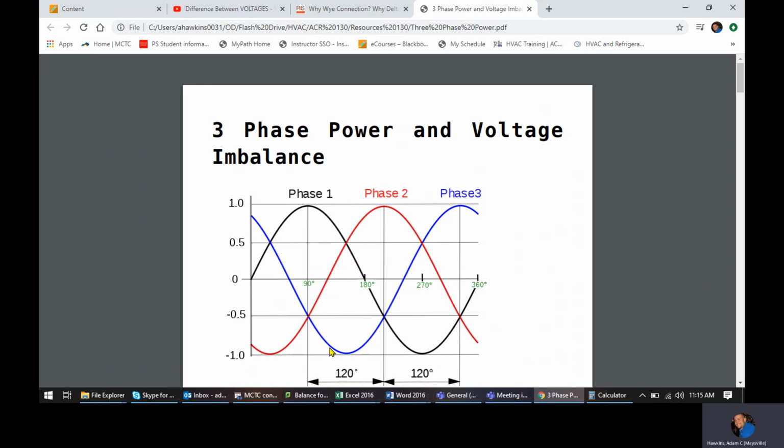So power is coming from the power plant or wherever, however it's coming in on three phase, and then they're just grabbing one of those legs, running it through a transformer, and then splitting that phase two different ways, and so they're running it into your house as two legs of 120 volts of the same phase that are completely equal and completely opposite.